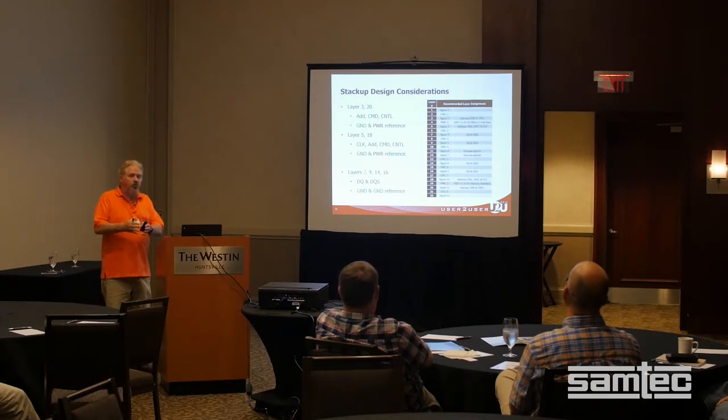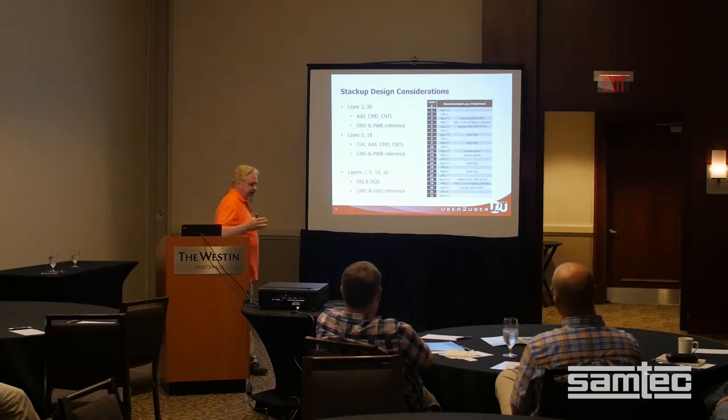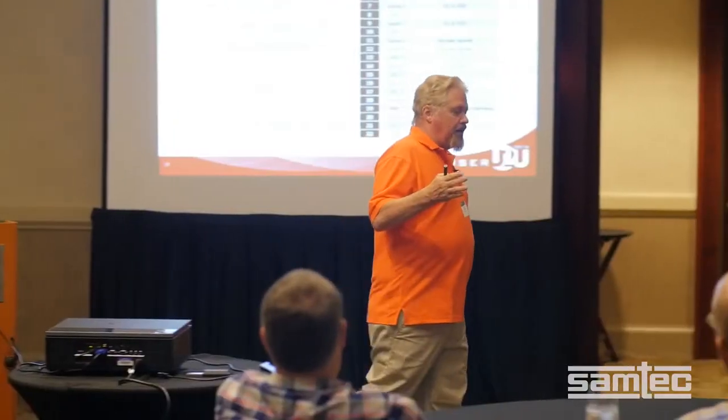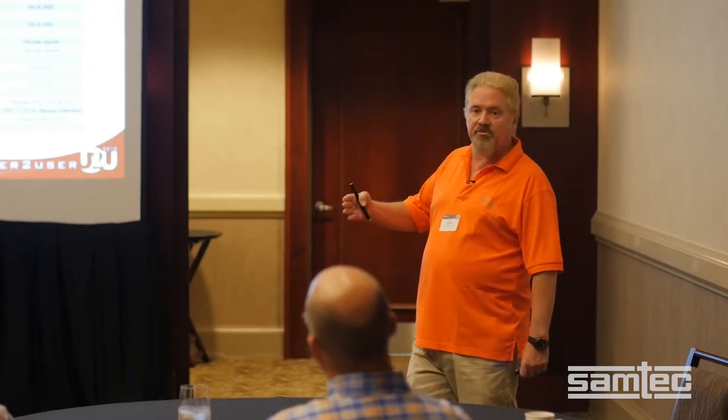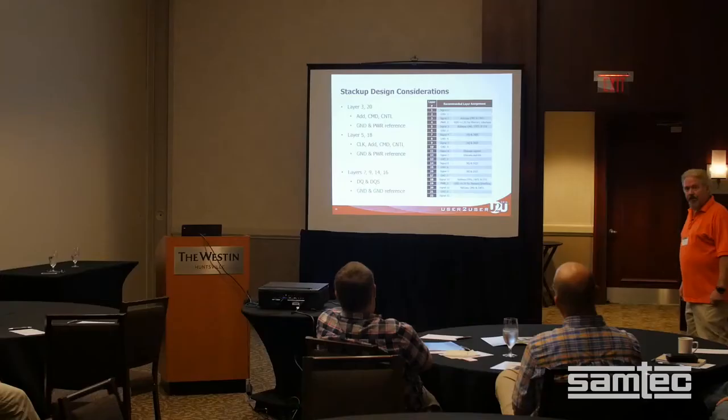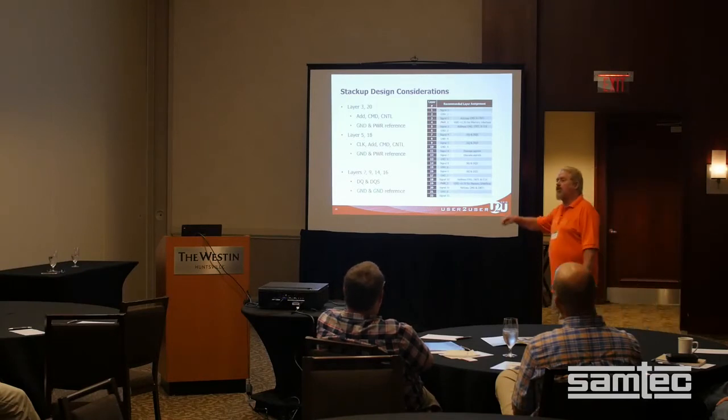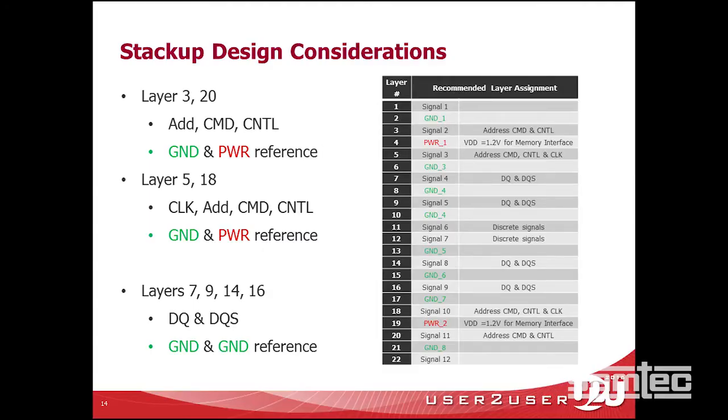So you need to hold to what the spec is, and unfortunately the spec can change depending on the controller. What layers do you use for references? For example, a DIMM chip tells you what the references have to be for the data control. If you do not follow those and you're using DIMMs, you'll change references when you go to the DIMMs, and there's a big chance your parts won't work. And if you're not using DIMMs, then what references do you use for the DQs and the addresses?